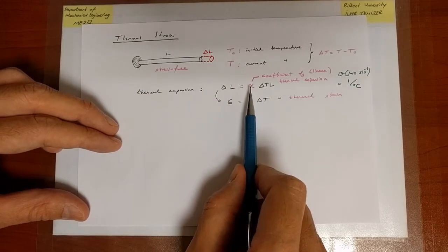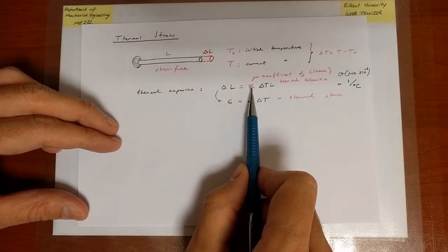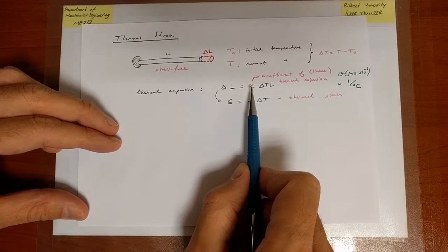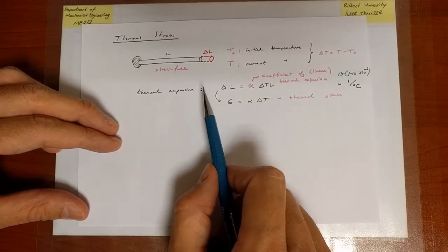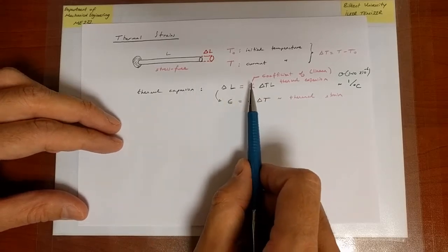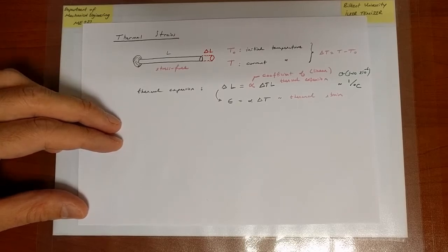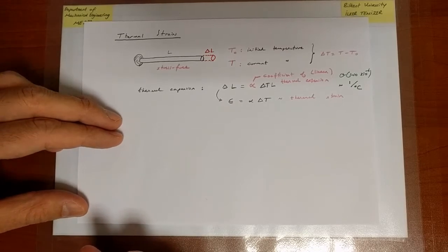Turns out that you can also have a coefficient of thermal expansion that actually is negative. So in other words, you heat the material up, it contracts, or you cool it down and it expands. And those materials you don't find widely in nature, but just like for the case of the Poisson ratio, you can engineer them. All right, so well, this is our observation.